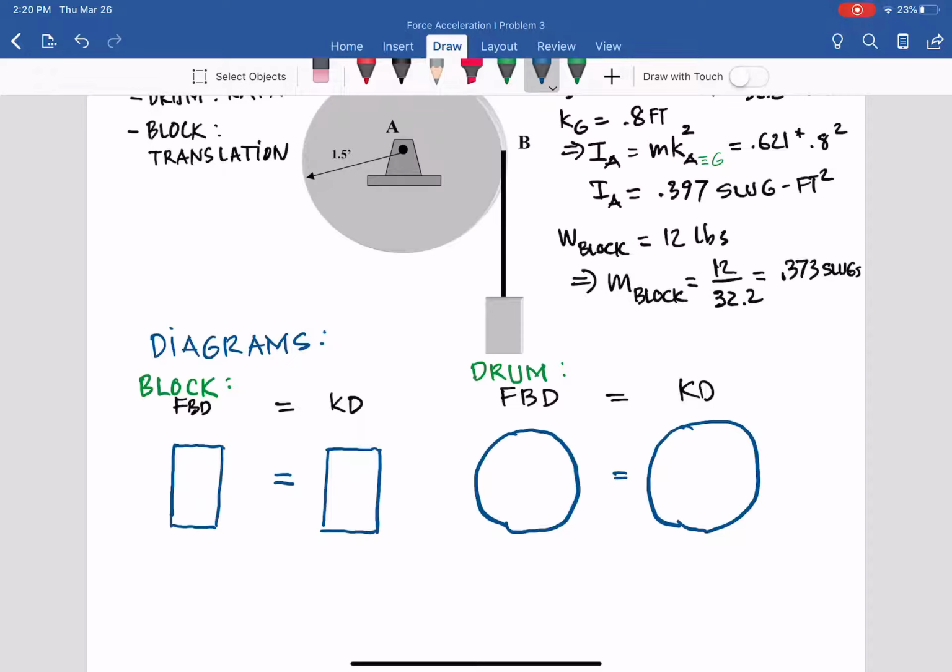And then go ahead to draw the free body diagram on the left, and the kinetic diagram on the right. So let's start with the block. You see the weight, 12 pounds, so it will be going down, 12 pounds. And this body is in translation, and the tension of the cable will be T. In statics, you put that equal to 12 pounds, but in dynamics, don't put that, T is unknown. And the body, of course, as you can see, tends to fall freely, so it's going down.